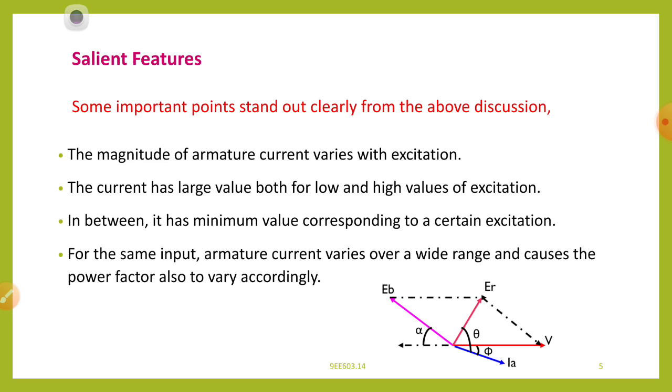This is a very familiar vector diagram. V is the applied voltage, EB is the back EMF induced in the stator conductors due to the field of the rotor. The field of the stator is the rotating magnetic field axis, and the field of the rotor is the rotor magnetic axis. Theoretically both coincide at the synchronization condition.